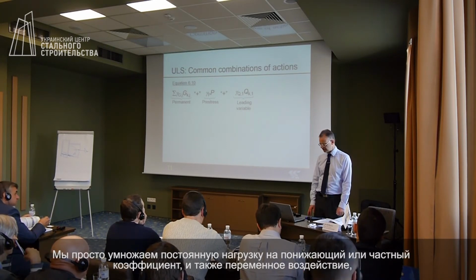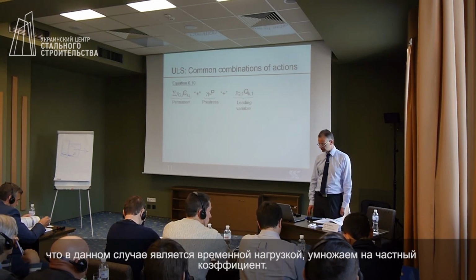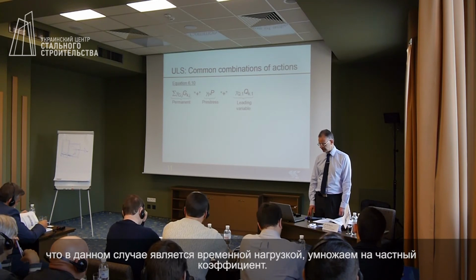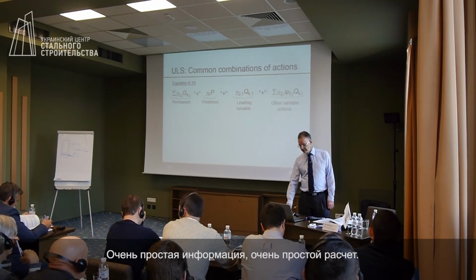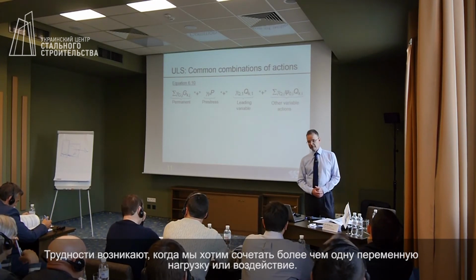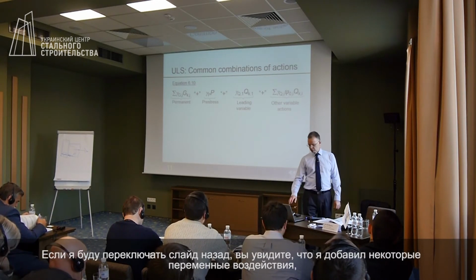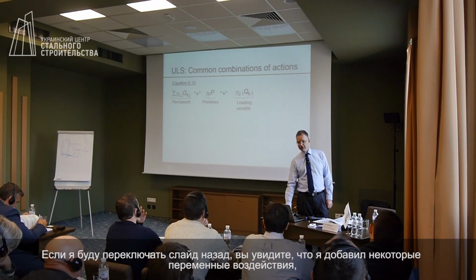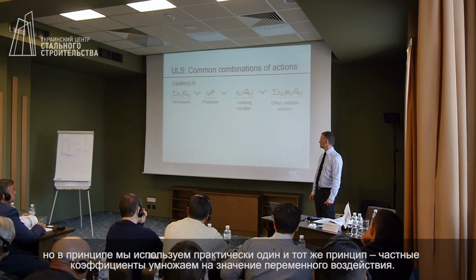The permanent actions multiplied by a load factor or a partial factor, a variable action, which in our case in this room would be the imposed load, multiplied by a partial factor. Really straightforward stuff. The complication comes when we want to combine more than one variable action. So if I flick backwards and forwards on these slides, you'll see that nothing is changing. When I add in an additional variable action, those terms stay precisely the same. So the same partial factors multiplied by the same actions.